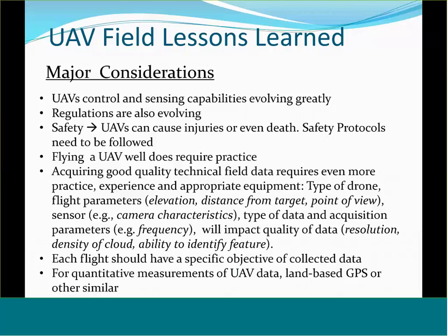And so in order to acquire this good quality field data, it's going to require even more practice, more experience, and the appropriate type of equipment. You need to consider the type of drone that you're using. You need to consider how you're flying it. How far away are you from the target? What's your elevation? What's your point of view of the object you're trying to see?